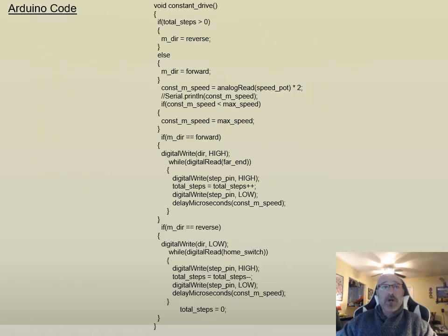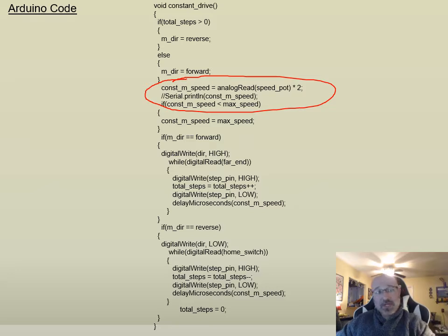And a little bit more here again. Even though we have the option for closed and open here, if we have the open, a lot of the programming is still pre-programmed in. We're not using the sensors anymore, but it's still all within the same coding here on our Arduino. So we're going to set our times. Okay, this is our start time, this is our stop time for motion, this is our speed programmed in here, and all that's going to be included in our code as well.